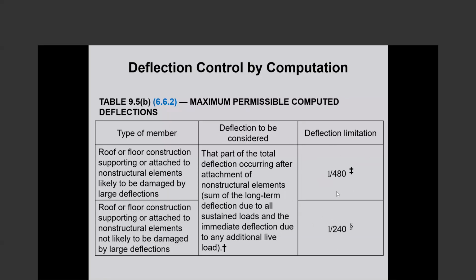That part of the total deflection occurring after attachment of non-structural elements, which means the sum of the long-term deflection due to all sustained loads, so long-term deflection due to all sustained loads and the immediate deflection due to any additional live load. Okay, so please try to understand this.